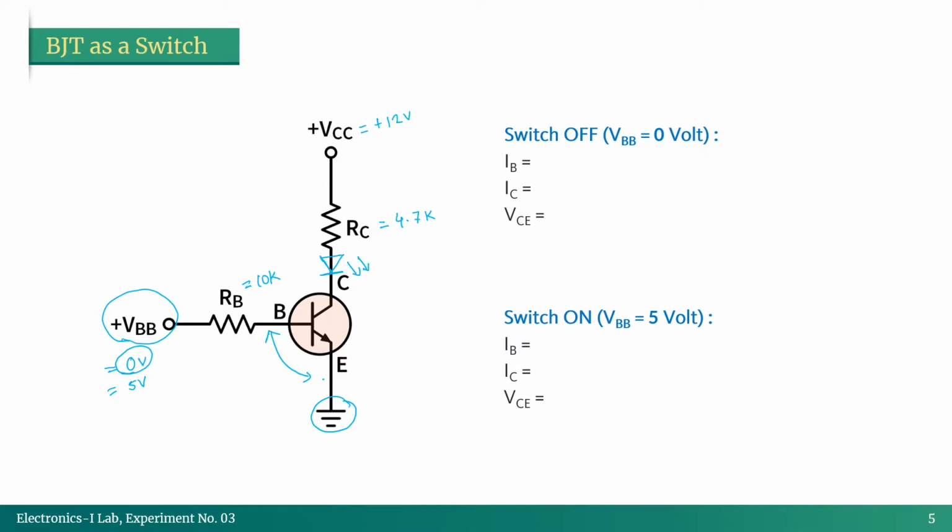So this junction, emitter to base junction, is actually reverse biased, and as we are already giving 0 volt at the VBB, this is a positive volt, we know the collector to base junction should also be reverse biased. So both of these junctions are reverse biased, which fulfills our cutoff mode condition. That's why we are in cutoff mode.